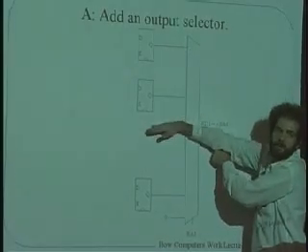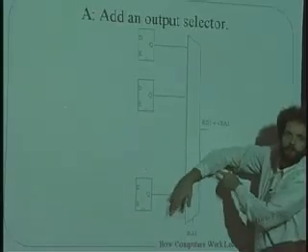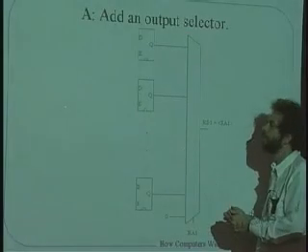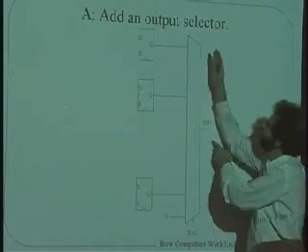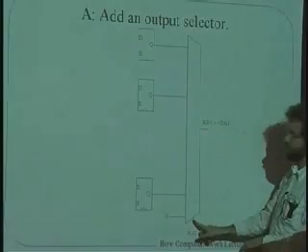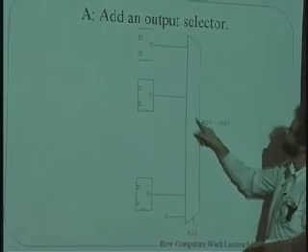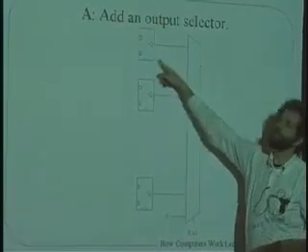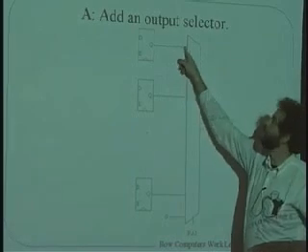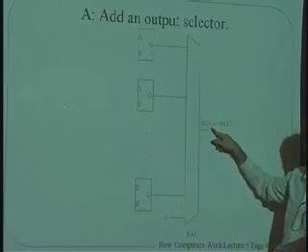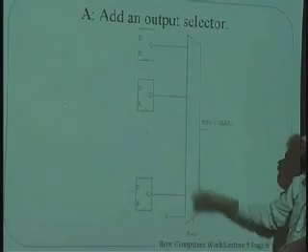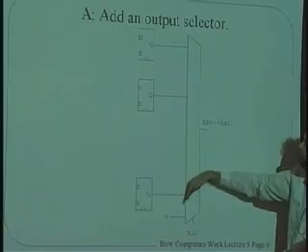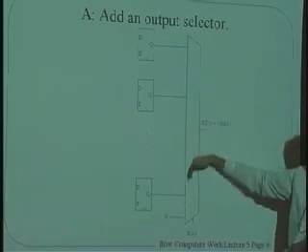Okay, if you remember the selectors we used before to steer how the data moved one way or the other inside of the circuit, this is the same thing. If we wanted R0, we would put a 0 into here, and the selector would choose, we'd draw a red line between here and here, saying that we're going to choose the output of this guy up here, all 32 bits of it, to get steered down to here and come out. On the other hand, if we put a 1 into here, we're going to choose this one. A 2, we'll choose this one, 3, 4, 5, 6, 7, all the way down to register 30 down here.